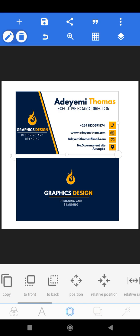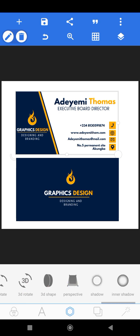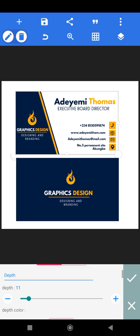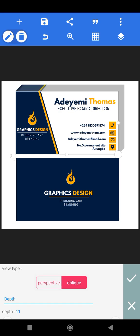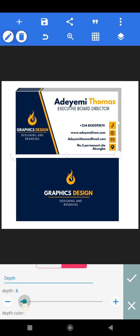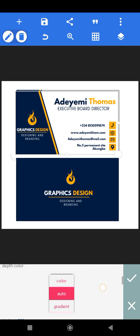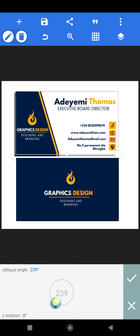What you now have to do is go over to your, I'm just trying to be fast, to your, what's it called, 3D. You enable it, then just put it to oblique, then reduce the depth to 5, or let me say, it's okay like that, make it 3. Then come down here, change this like this. Yes, make sure it is like this,